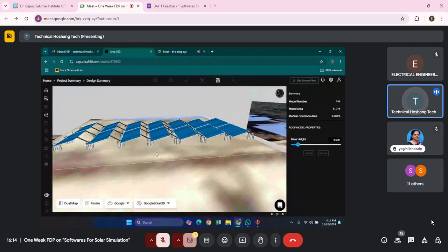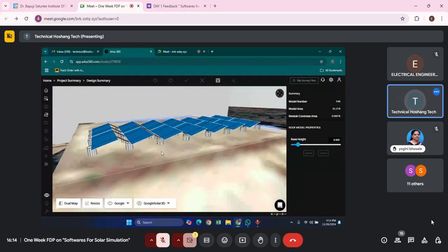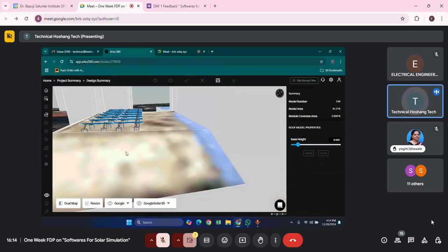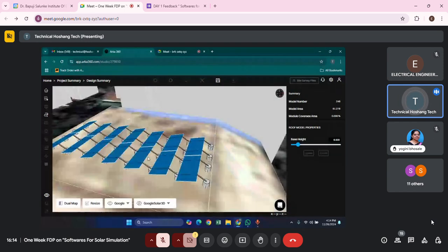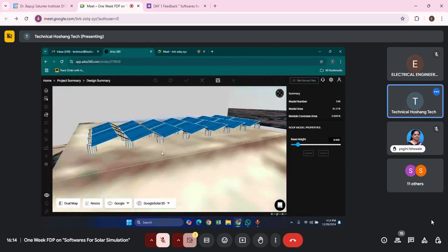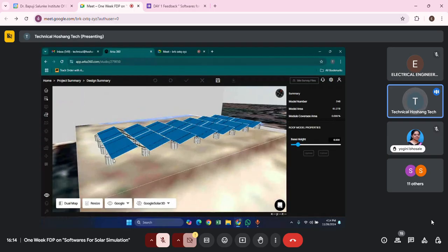This is a different type of structure which you can use. It has 4 legs for each panel. On flat roofs or flat ground structures, you can use this type of structure. While fixing this type of structure, you have to clean the lower surface properly.